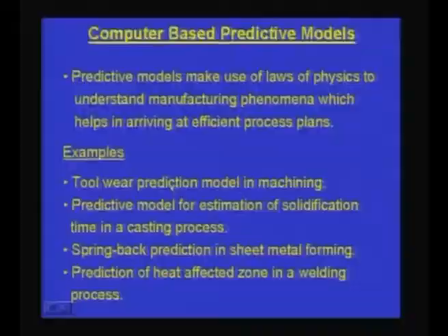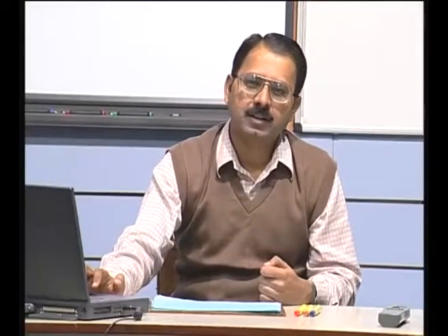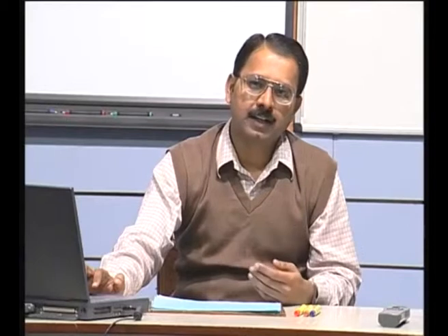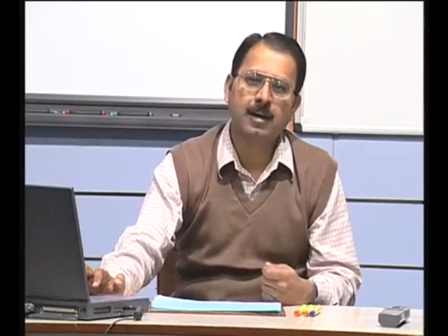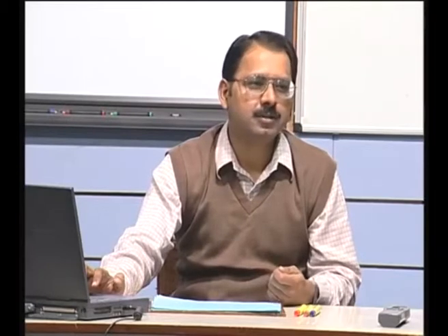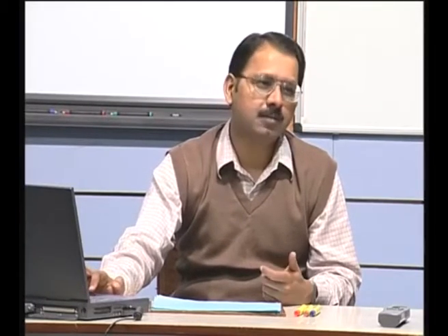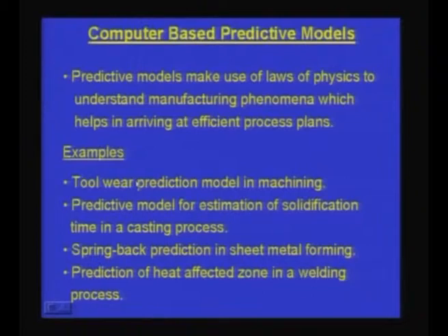If I have a mechanics based model which can tell that the life of the insert is going to be so many minutes, then that will help in deciding when the tool replacement should happen, or when the insert should be replaced. So, you are using a mathematical model, which may be analytical or computational or numerical, to predict what would be the tool wear.